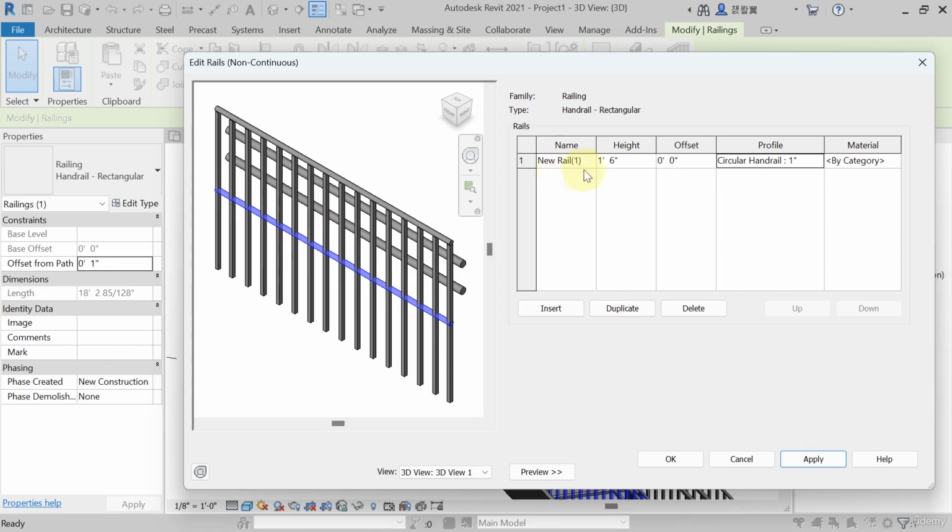Okay, so automatically now what happened, rail 1, this is which I have created, railing. If you want to give railing here, you can provide it. Again you want to enter second railing, hit on that, at what height you want that railing. So this railing we have created at 1 feet 6, means 1.5.